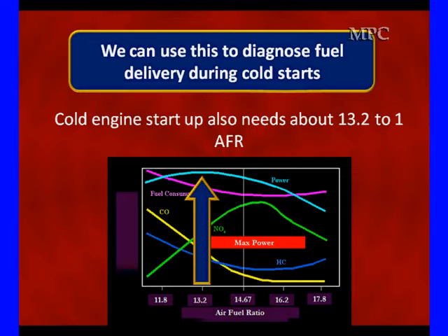So we can also start controlling fuel earlier and keeping it only as rich as it needs to be for engine operation. That's very important because we couldn't read the richness with a narrowband. We had to wait till it could finally get into closed loop. Closed loop now will come much faster.